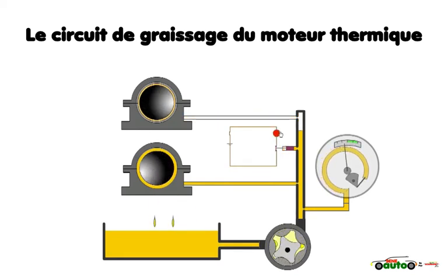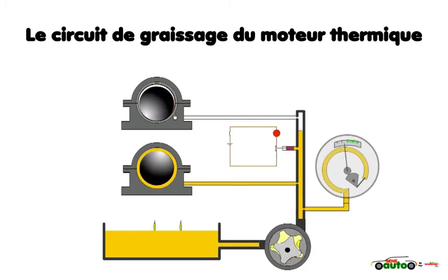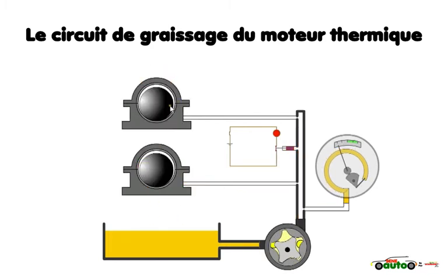Without the correct pressure, the oil will not reach the more remote bearings and they will be starved of oil. Now we have low oil pressure on the gauge and the pressure switch has activated, alerting the driver via the oil warning light. If this situation is allowed to continue, friction will cause the bearing to overheat and seize the engine. Note, the low oil pressure was caused by a worn bearing and not due to any issue with the oil pump itself. This is often the case with a high mileage engine.